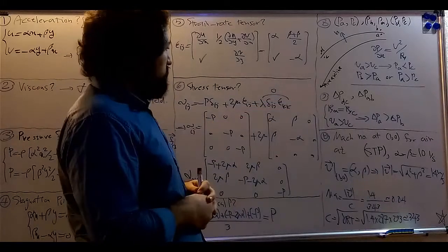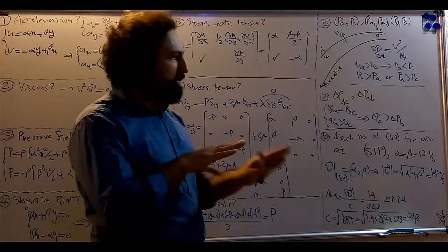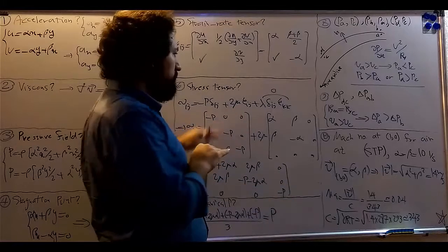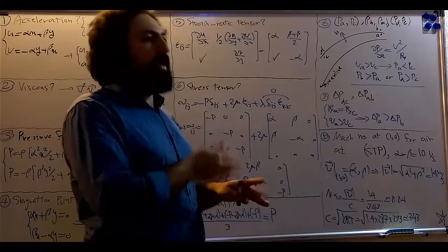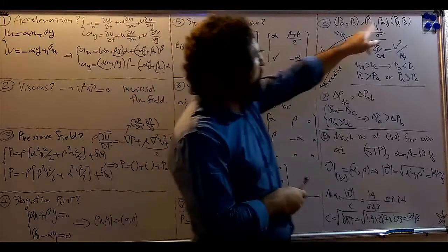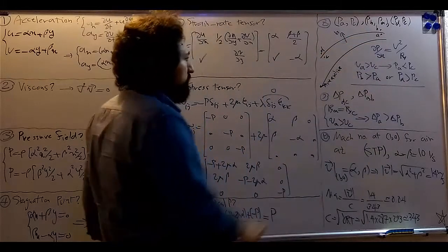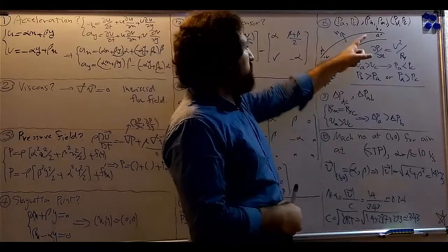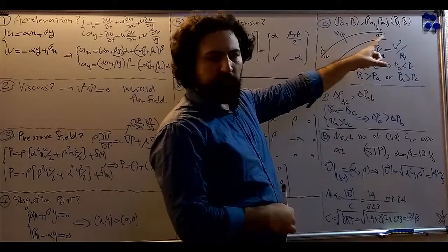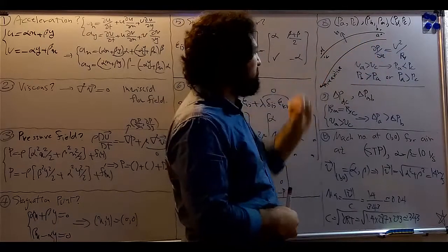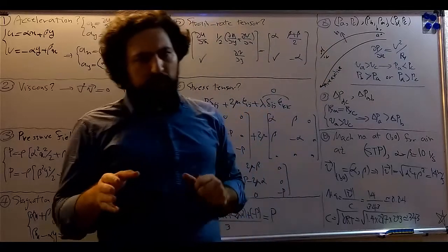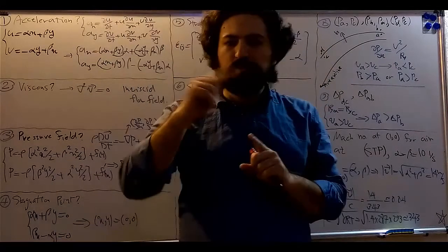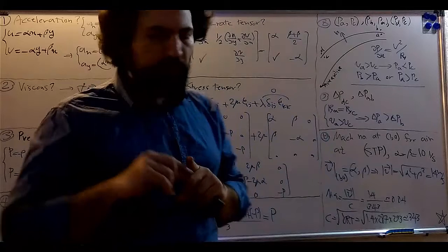Question number 9. Compare the pressure difference between points B and C and the pressure difference between points A and B. Again, referring to Euler's equation, the radius of curvature of the streamline at points A and C are equal because the streamline is assumed to be a circle.